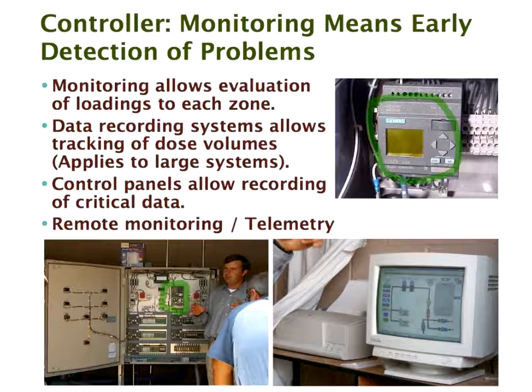Today, the PLCs can be set up so that each zone can get a different time, which was one problem we did have with PLCs, that all zones were getting the same amount of time, and now they can be set up with each zone getting a different length of time, because you might find that one zone, for some reason or other, has a different type of soil, and you want to vary the time according to the zone.